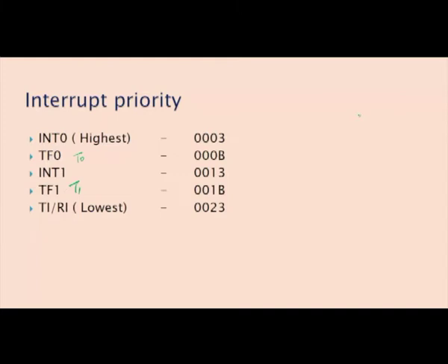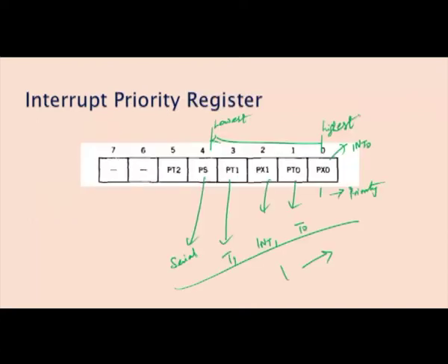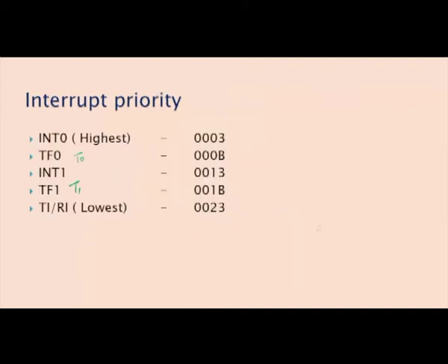Already I set it, right. Suppose you are assigning the priority, both INT0 and INT1 are assigned with the priority. So 1 0 1 0 0 0 0 0. So the word is 05H. Okay. So now you write MOV IP, 05H. So what it represents is that the interrupts both INT0 and INT1 are active, and also I have assigned the priority for INT0 and INT1. Okay. So now both are activated at the same time.